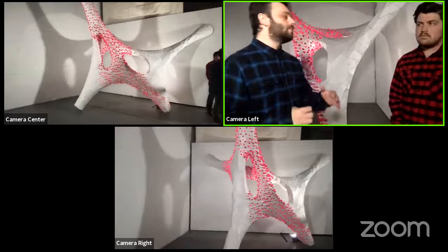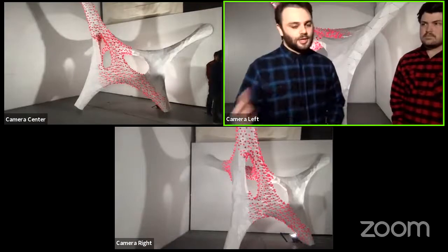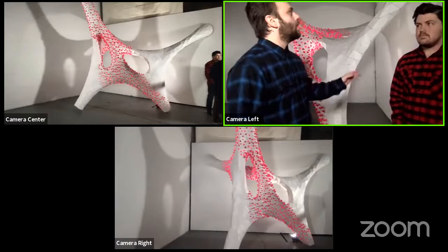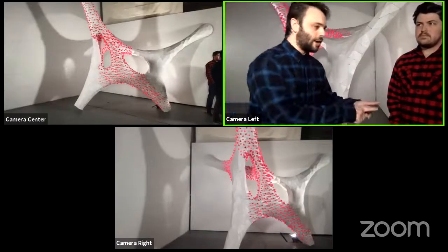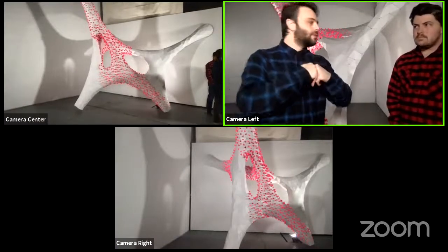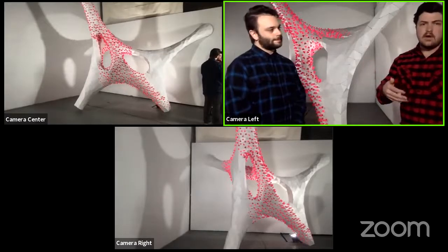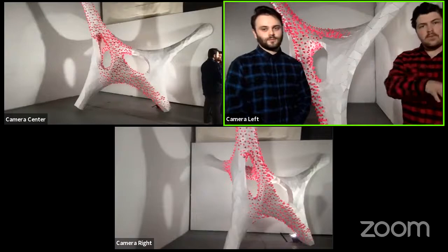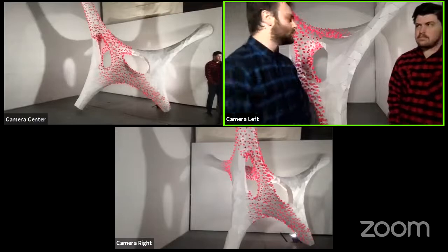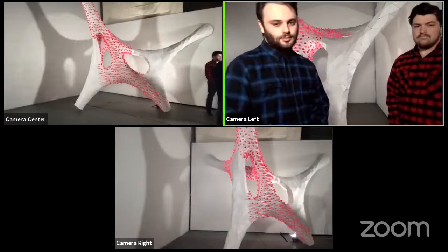We used Grasshopper, which is the visual scripting component, and a combination of C# custom written scripts to generate this form, and also especially to take that parallel data from the edge information and put those onto the tabs so that we could then pair each tab to each other. Yep. The only other software involved was just the laser cutting software. We were able to export directly from Rhino to the laser cutters. Yeah, it was a pretty all-in-one solution with the custom scripts in Grasshopper and Rhino directly to the laser cutter. So that was great.